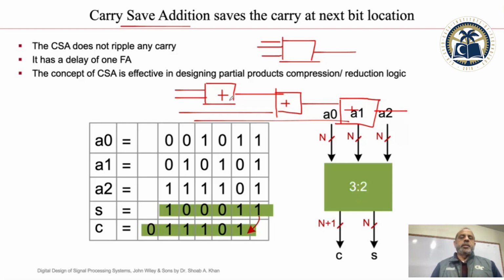On the other hand, if you are using any other adder where you compromise area over speed, like carry select adder, conditional sum adder, like we saw earlier, then it'll take a lot more area. So the best and very simple strategy is that when you are adding more than 2 numbers, let's say 3 numbers, you save the carry, you don't propagate the carry. Okay, carry propagation means that you keep sending the carry to the next full adder, to the next full adder, and it keeps adding. Don't do anything.